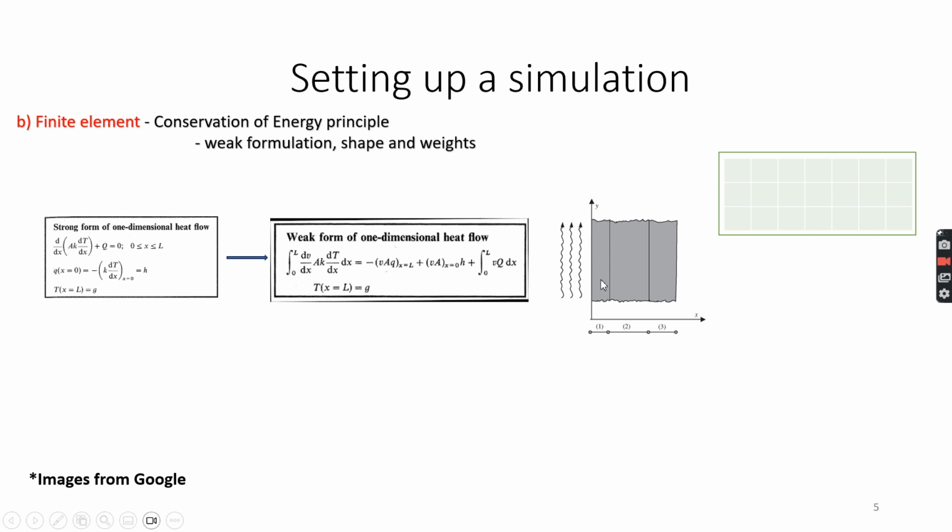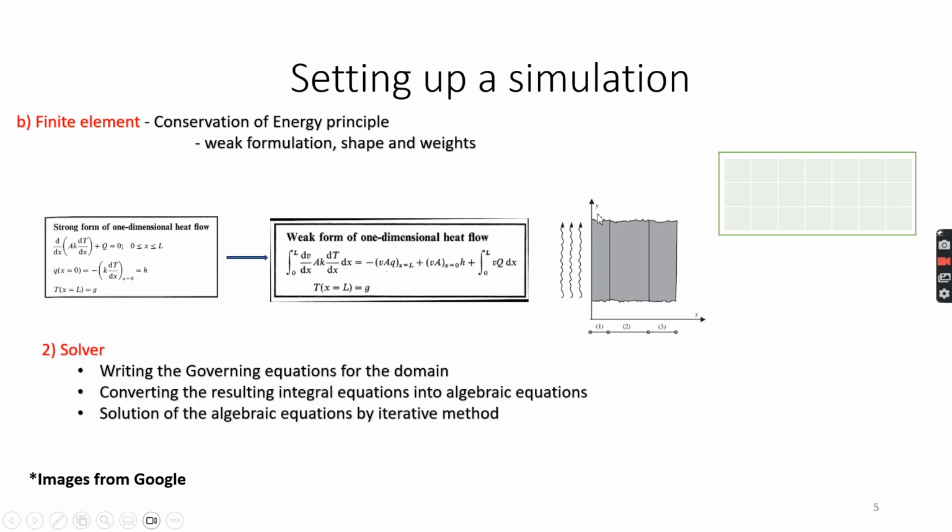So for example, if I wanted to focus more, or the area of interest is this part over here, then I discretize this part more. As you can see over here, since the width of this part is less compared to this one, I could give a greater weightage for the shape function over here if I'm interested. So that is how it works for the finite element method.